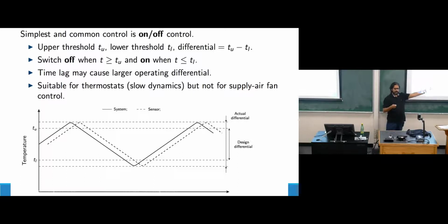So in some sense, you will let the temperature increase from the desired until it reaches some upper limit, after which you will start controlling the reheat and the valve so that the temperature starts dropping. You will overshoot your desired temperature, hit some lower value, and then go up and down again. So this sort of bang-bang control is very commonly done, and this is an example of a rule-based controller. Okay, this is how buildings are set as rules.